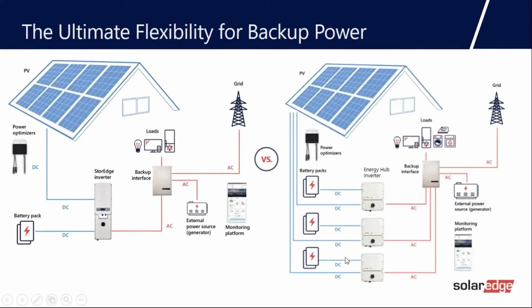If you use Energy Hub, it becomes a grid forming inverter that allows other inverters to sync their sine waves to it. So that's huge. That means eventually you will be able to connect existing sites. If you have an existing SolarEdge inverter, you can come out with an Energy Hub, a battery, and a backup interface, and you can AC couple.